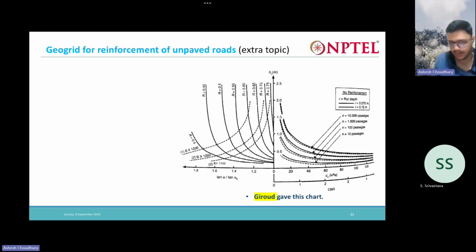But when we use geogrid, what happens is that, remember we use the pi plus 2 cu. Pi plus 2 cu is the elastic limit when we are using geotextile, remember, right? But in case of geogrid, it changes to pi plus 1 cu. That's the difference. Rest all the things are going to be the same. Okay, so directly from these charts we can find out the h naught as well as the reduction in height, so the new height.